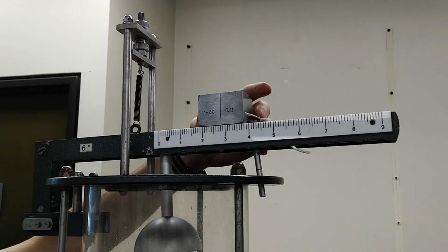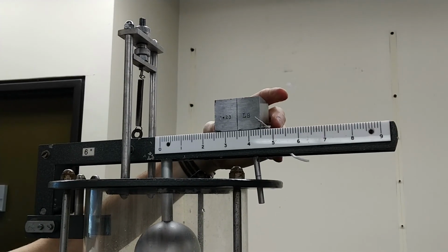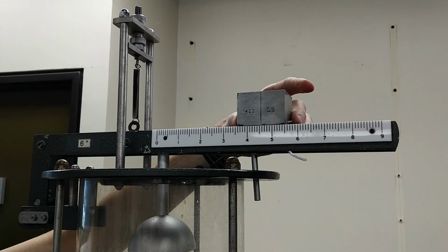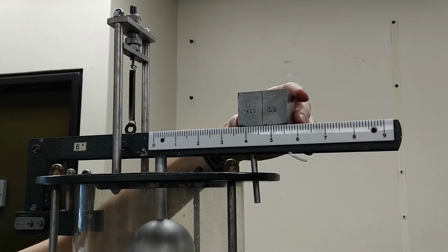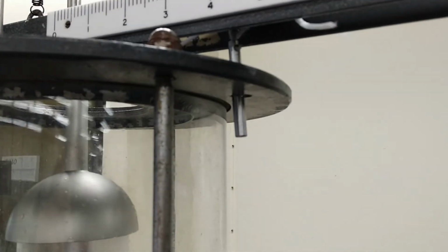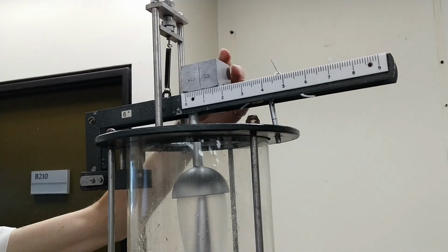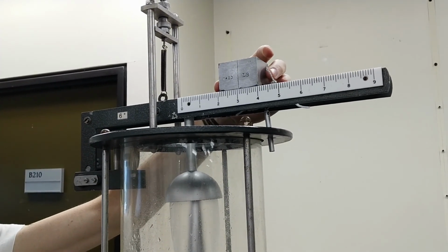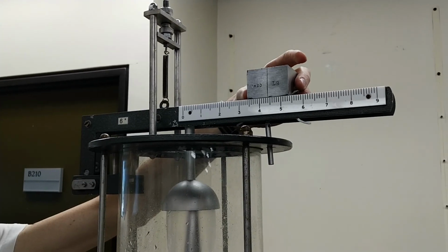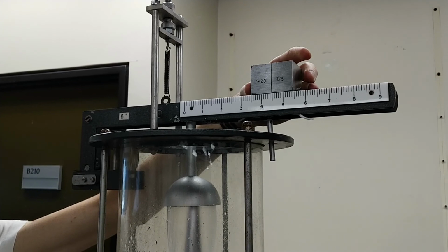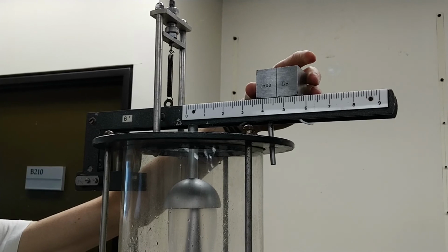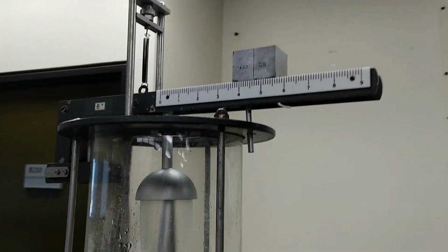As we have changed the mass of the plate, we must then remeasure the distance Lw at equilibrium. The pump is turned on again, and the weight is adjusted until the balance system is level. Finally, similar to the flat plate part of the experiment, the mass flow rate of the system will need to be determined in the same way.